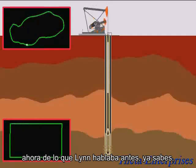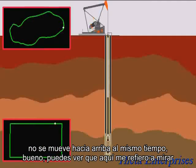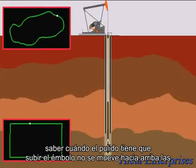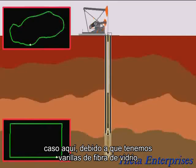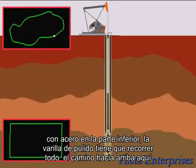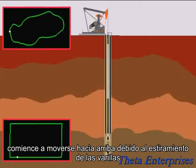Now, Lynn before was talking about the stretch of the rods, that when the polish rod moves up, the plunger doesn't move up at the same time. Well, you can see that here. Look at the surface card. When the polish rod starts to move up, the plunger doesn't move up. The rods have to stretch first before the plunger moves up. And actually, in this case, because we have fiberglass rods with steel on the bottom, the polish rod has to travel all the way up here, like halfway up on the upstroke, before the plunger starts to move up because of the stretch of the rods.